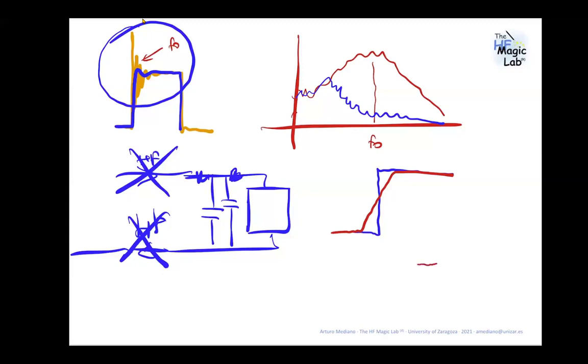In one of the talks from the first day seminar, we saw that if you have a signal being switched at a fixed frequency and we apply spread spectrum, as we remember from Florian's talk, the spread spectrum spreads the energy in the spectrum and the peak is reduced. This is another technique to kill the source. In this last example you are not exactly killing it, but you are reducing the origin of the problem, the energy at the origin of the problem.